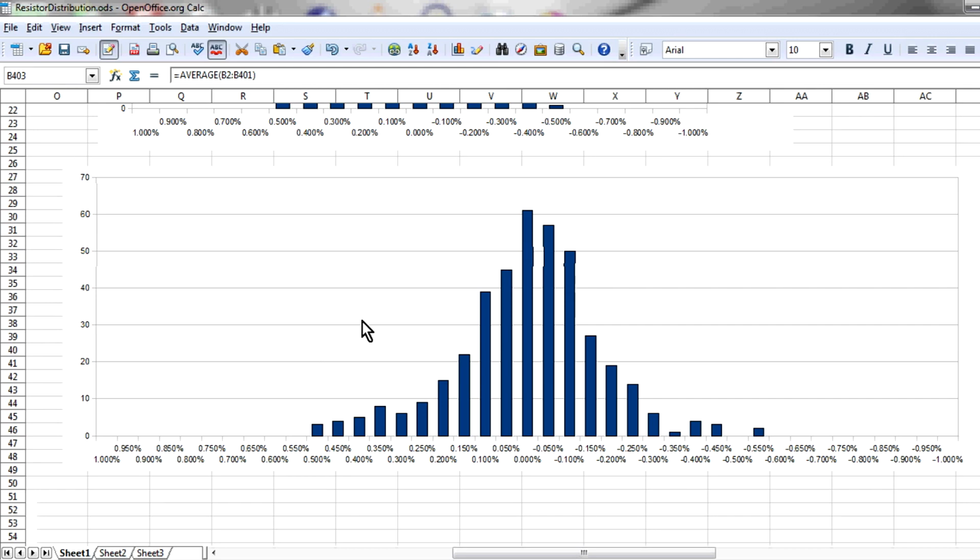as a lot of people claim, that they manufacture, say, 5% resistors, and then they test them all, and the ones that pass to plus minus 1%, they mark them and sell them as plus minus 1%, and the others they sell as plus minus 5%. Well, that's clearly not the case, because if that was the case, I would expect a response which is much shallower. It'd still kind of be like the top sort of peak of that Gaussian response.